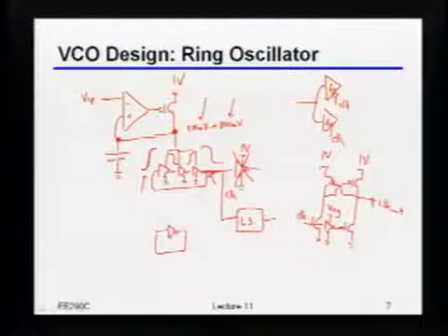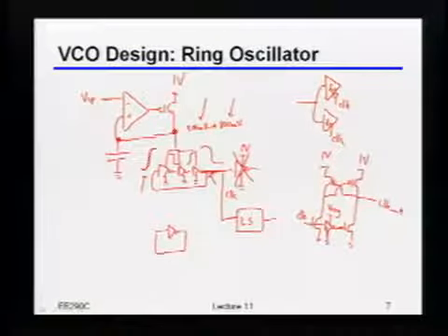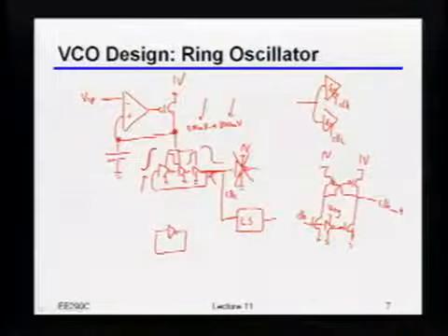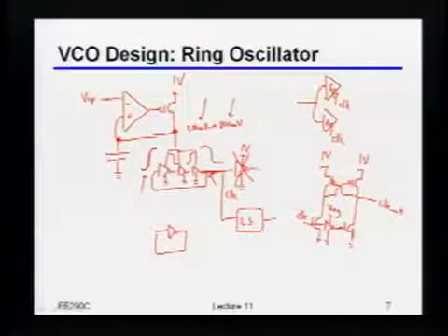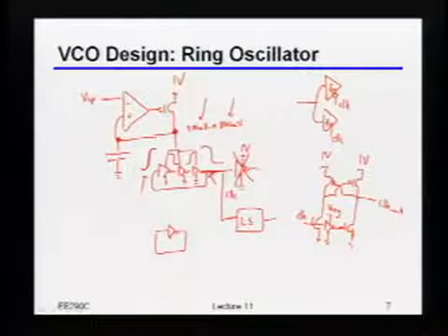In contrast, to make this go low, I have to go through this inverter, which is on the regulated voltage, then turn on this NMOS, and pull that node down. So the delay from those two paths is completely different, and even at 1 voltage it'll be wrong. If you change that voltage around, it'll move around in terms of how wrong it is.